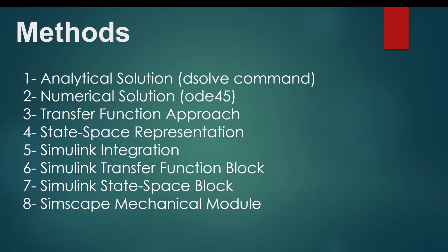So these 8 methods are: 1. I'm going to find the analytical solution of the problem using the dsolve command. Second, I'm going to find the numerical solution using ODE45, since, as you probably know, not every equation has an analytical solution, so you must be familiar with numerical solutions.